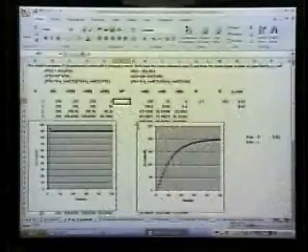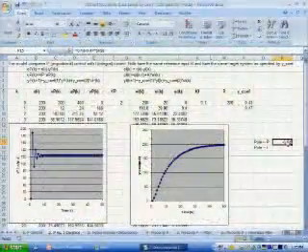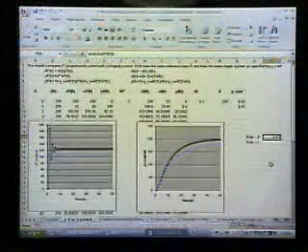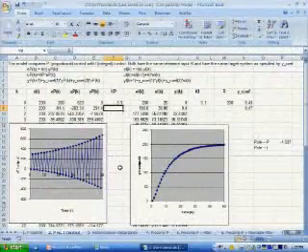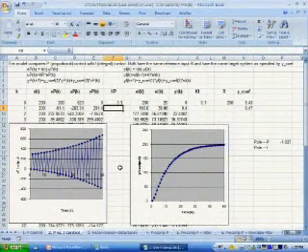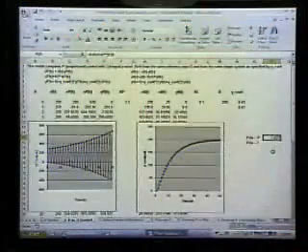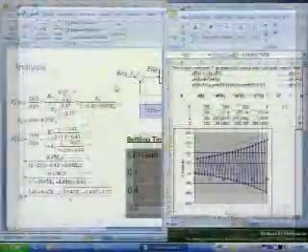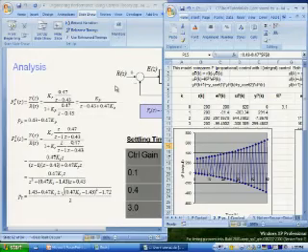It's also a little bit negative, so you get some oscillation. What happens then when we change this? Suppose we change it to 2. Okay, bigger pole, also negative. Oscillation, longer settling time. What happens when we get to, I think we're looking at 3.1? I've forgotten the point at which it becomes unstable. Okay, that's unstable. What's the pole? It's outside the unit circle, right. So that's exactly what's going on in this system. So the poles, in this case, really tell us a lot.